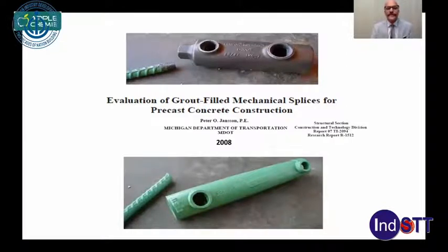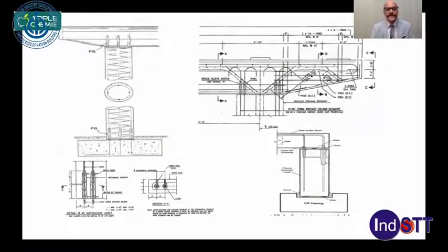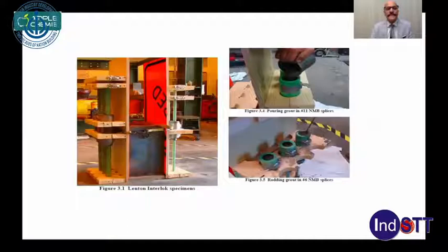This is what I mean by the coupler. These are the couplers and the extending pieces. These are used for the extension and continuity of the reinforcement. And there are various uses of it. You can use it in infrastructure, like what I have shown over here. This is a huge column and beam connection, or a vertical connection also. These couplers can be tested in the laboratory. And the grouts used in the coupler are even more important, because the coupler basically is a mechanical thing and it can be tested for various mechanical parameters.